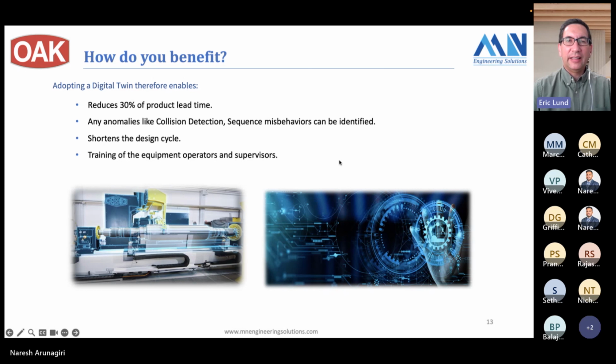What works even better then is if we take the digital twin, apply it to that training device, and then let the operator, our customers' operators, practice using the machine and learn how to use the machine. And not only are they learning the layout of the HMI, but they also see the consequences of the choices they make when they operate the machine. They see how the machine runs. They see what happens if they don't do the right sequence, and potentially damage that would occur, all safely within a virtual environment where it doesn't need to have replacement parts.